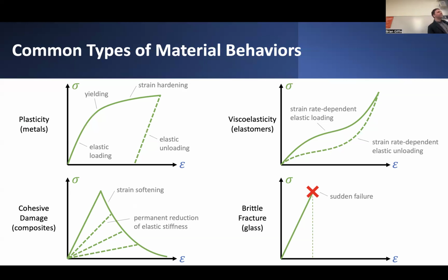And it's usually associated with things like metals. Think steel or other materials, aluminum, copper, things like that. Most metals exhibit this elastoplastic behavior and experience effectively a form of permanent deformation. It's like what would happen if you took some bar, stretched it, and then removed the load, and it stayed permanently stretched after you took the load off. That's effectively what this behavior represents.